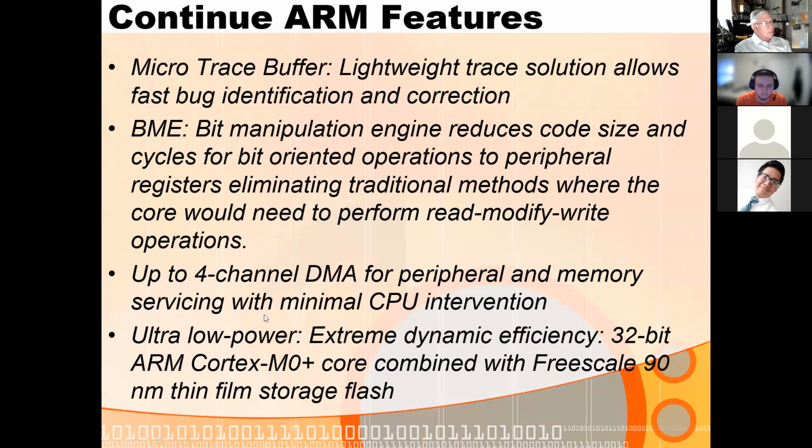Anyway, it's a very efficient chip. It can get down to very low power levels because it has extensive abilities to shut down various parts of its operation. Every single module, every single GPIO port has a clock that can be turned off. And as you know, on most integrated circuits with CMOS gates, if they're not switching, the leakage currents are usually small.